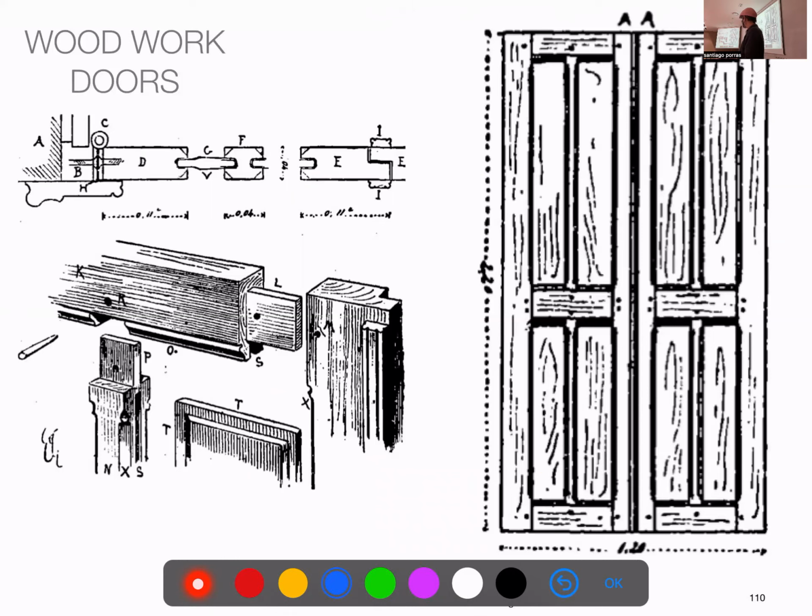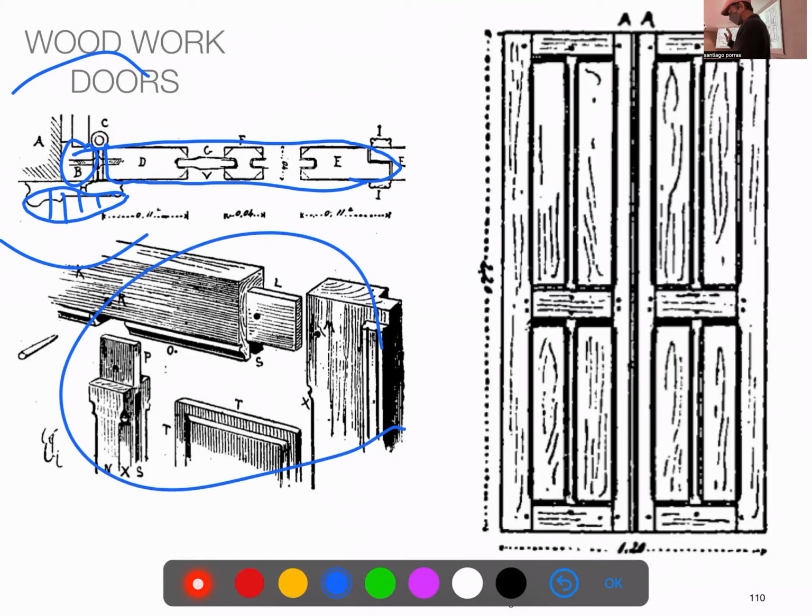So door, again, in old days, doors were made on site. I had to detail them. This was done just until the generation before me. So when I started, I almost always used catalog doors. But it's interesting to know how they are made. Actually, you always need to have the frame, the door sheet, and then one element to cover, right? One frame to cover these slits. And then if you have the total detail, the elevation and the section, then the large scale detail is in context, it's very easy to understand.